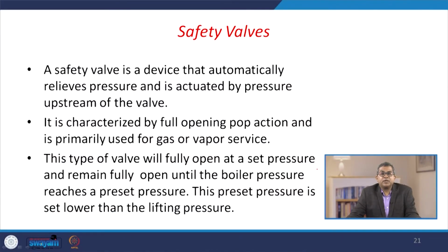So when we talk about safety devices, safety valves come into the picture. A safety valve is a device that automatically relieves excessive pressure and is actuated by the pressure upstream of the valve. It is usually characterized by a full opening pop action and is primarily used for gas or vapor service.